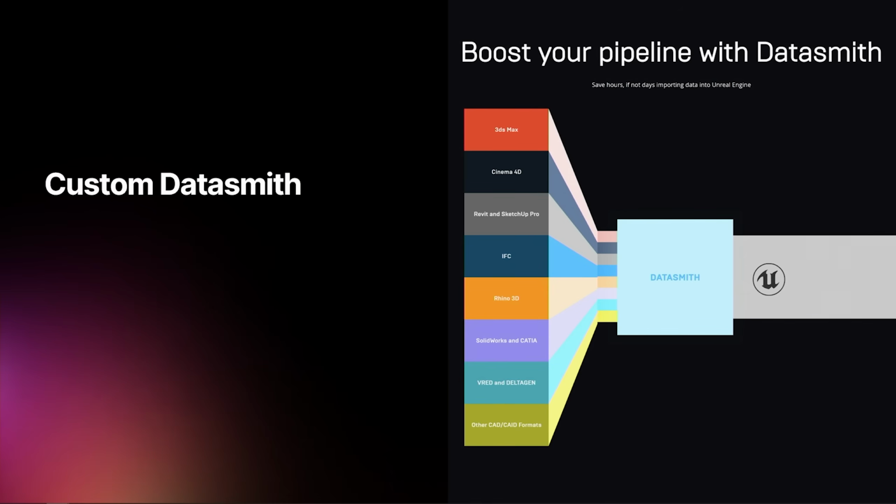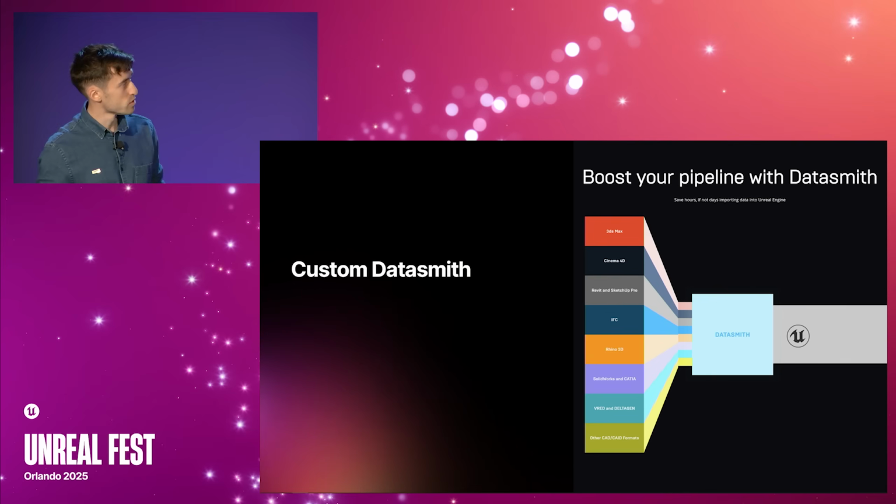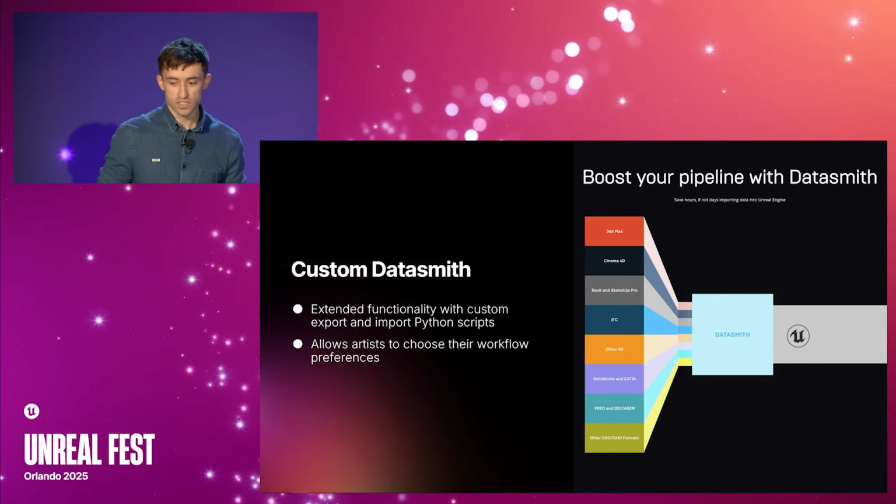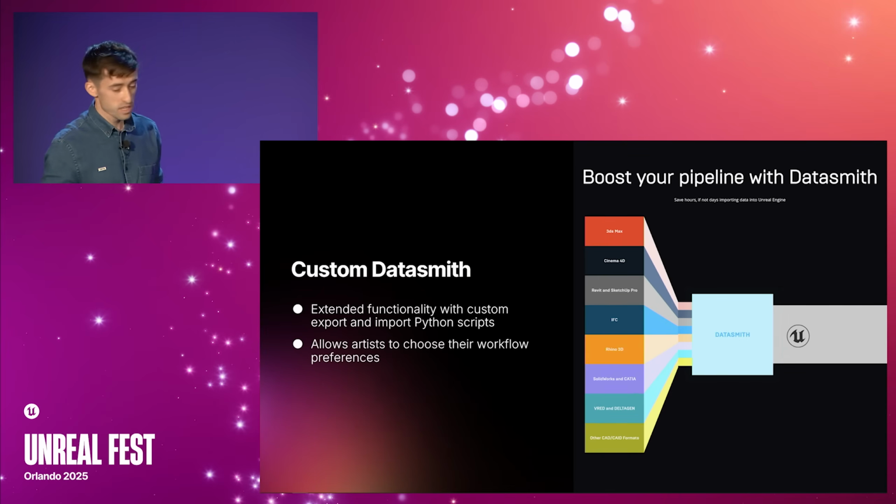If you're not aware, Datasmith is a plugin for transferring data from 3ds Max and Cinema 4D and other CAD tools to Unreal Engine. However, there's some problems with the default version that we needed to extend. So we have extended functionality in the form of some export scripts from the DCC and a custom import script when re-importing a Datasmith file in Unreal Engine. This allows the artist to choose their workflow preferences.